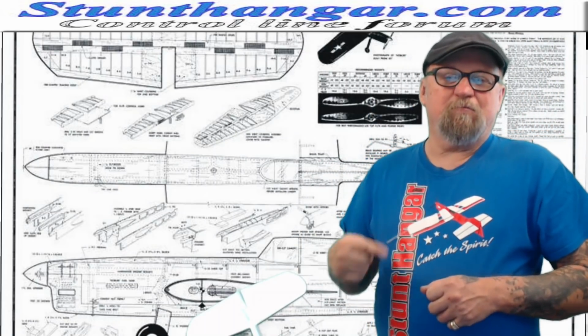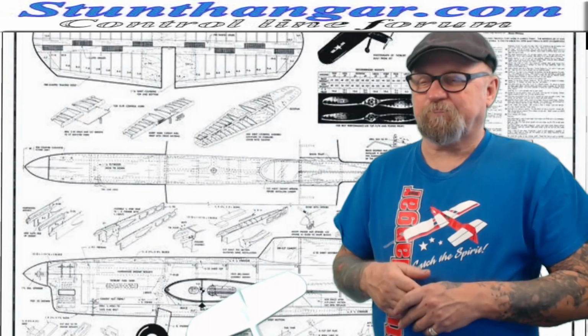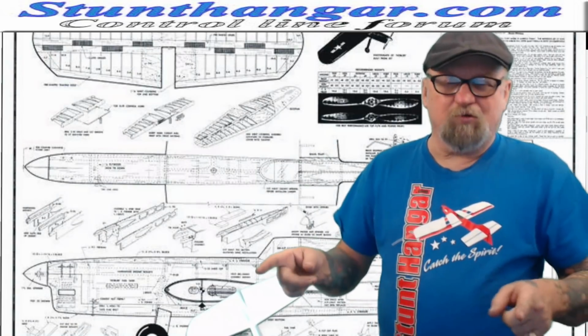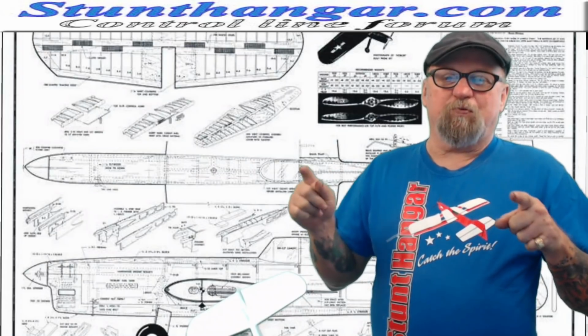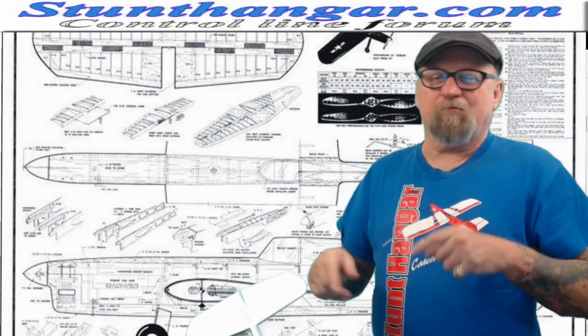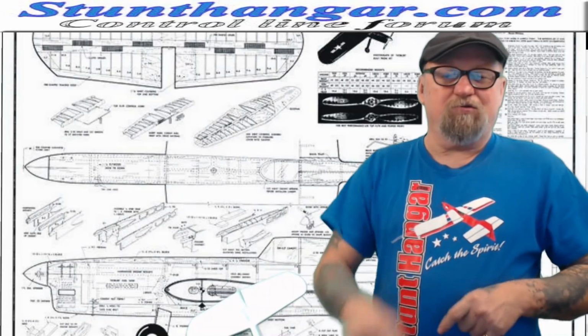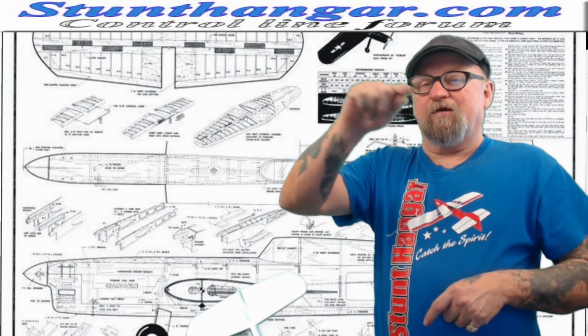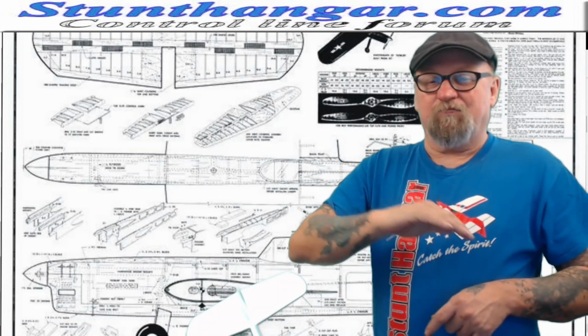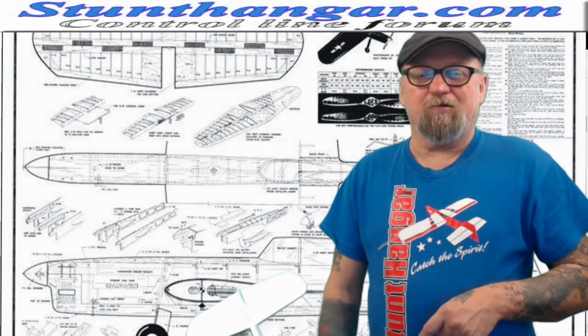After building many airplanes, you'll know that you want a 10-inch chord or an 11-inch chord, and you want the center of pressure 3 inches back or 3.5 inches back, whatever. You draw a line. You take your shoe, you go from the leading edge to the high point of the wing, and then follow that curve on over to the trailing edge.